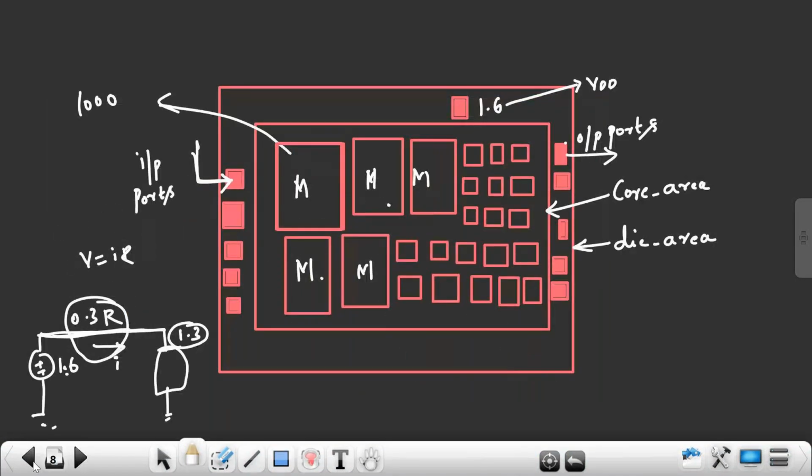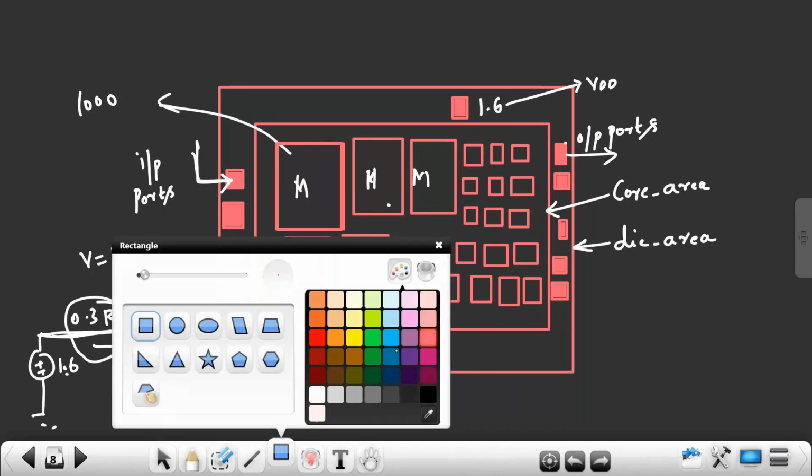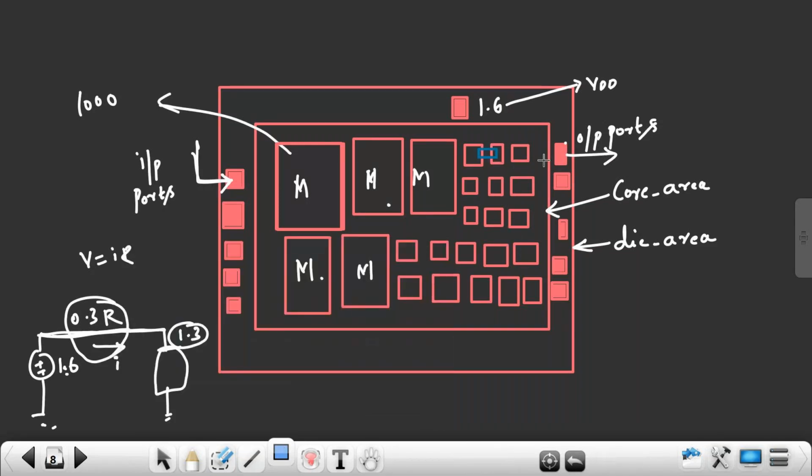So already CTS is built now, but only the clock tree is built. Only clock signals are built. Apart from that, other signals are not built. So connect these standard cells by using what? Metal layers. Connecting the standard cells using metal layers is called as what? Routing.